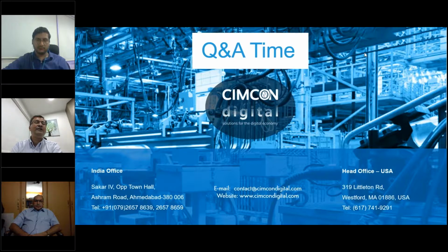You cannot have a different platform or different devices everywhere in the world, because otherwise you are creating another silo and another mess. The platform approach is that all these devices, connected either on Modbus or other PLC protocols, or OPC standard protocol, or wireless, Zigbee or Wi-Fi, come onto one single platform. That is where the platform plays a role, because if you connect every machine with a different device, you can understand how difficult it will be to maintain, because every device has its own product life cycle. When you're connecting, say, hundreds of machines enterprise-wide, it's very difficult to maintain those edge devices too. That is where edge management on a platform comes into the picture, using over-the-air firmware updates.